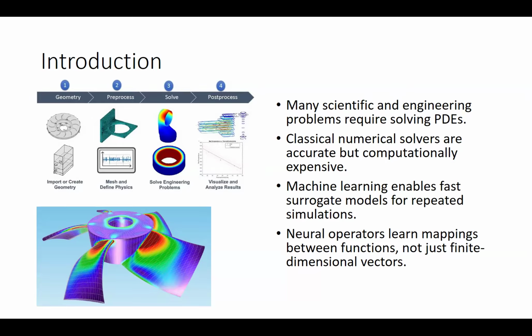And these methods are highly accurate, and that is their main benefit. But they have a major drawback. They are extremely expensive. They take too much time to compute the mesh and to compute all calculations. So if you want to change just one boundary parameter or change the mesh, you have to rerun everything, and you have to remesh everything from scratch. And because of that, this makes real-time control impossible, and multi-query optimization becomes impossible too.